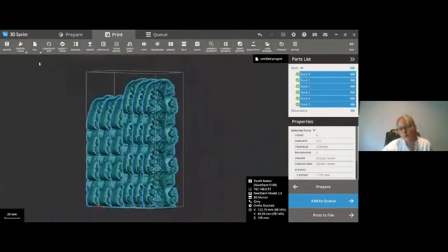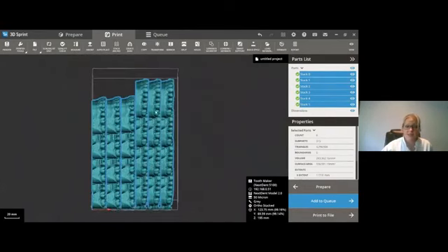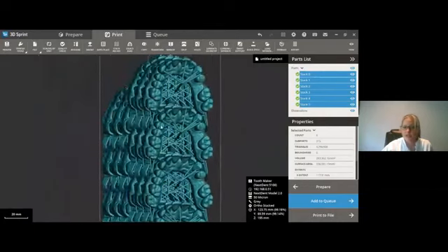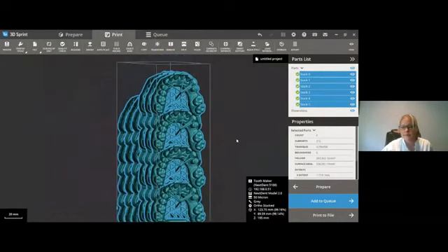Yes. Also, when you're going up to this max Z axis, you really need some extra stability, and that's why we've chosen the support style we have as well. Yeah, absolutely. And just to make sure everybody understands, your import models, so the input models, can be hollow or can be solid. So the algorithm will deal with both kinds of models. They just have to be watertight models, so no scans, and preferably have a flat base.